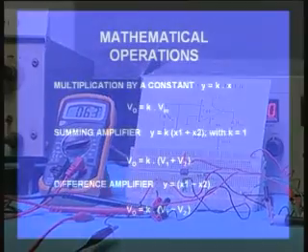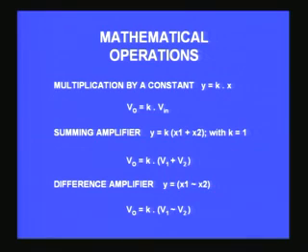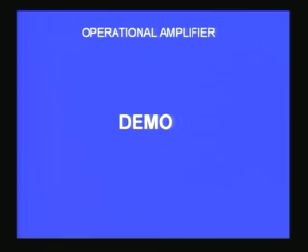Right. Now having seen the four configurations, you would recall that they gave you four different important circuits: voltage amplifier, current to voltage converter, voltage to current converter, and current amplifier. So the four different feedback configurations give you four different circuits which are close to ideal. All you have to do is use one or two resistors at most in the feedback configurations, and with a simple op amp like the 741 you will get four excellent amplifiers: a voltage amplifier, a transresistance amplifier, a transconductance amplifier, and a current amplifier.